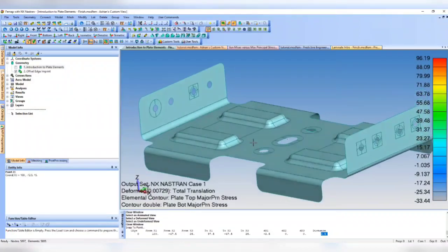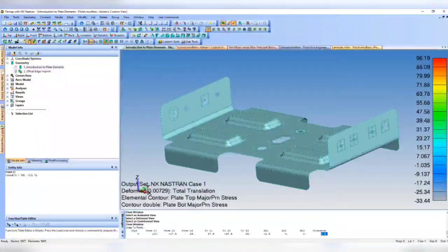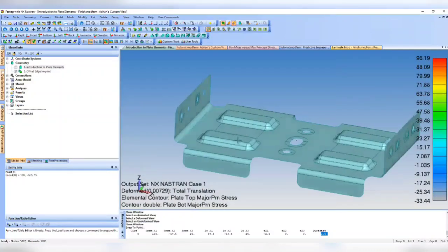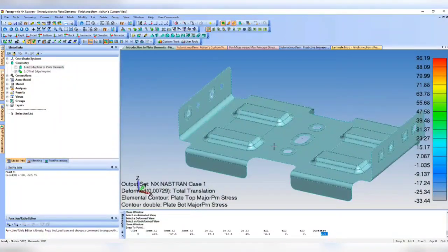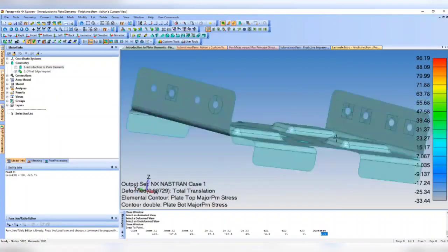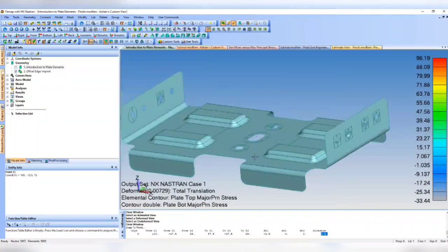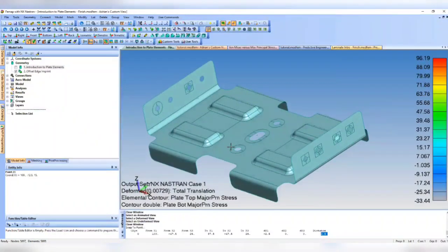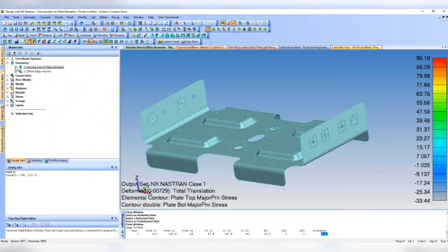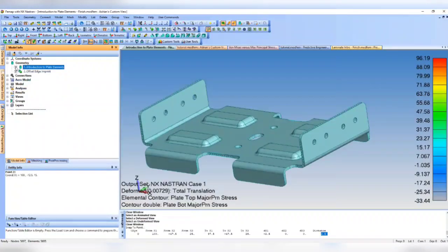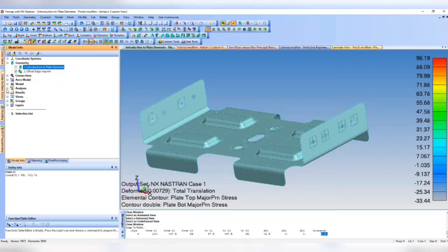I want to take a question, and one of the questions is, why not use 3D elements? The reason is because 3D elements are more computationally expensive, while shell elements can represent the thickness behavior just fine and model bending and loading conditions that you may encounter. Usually you're going to use shell elements for thin structures compared to the width directions. Yep, that is correct.